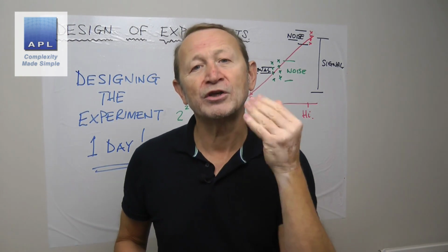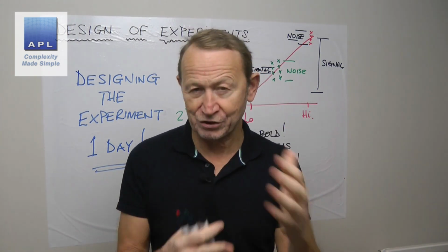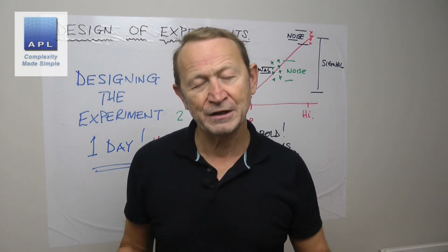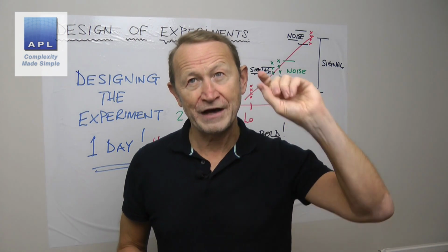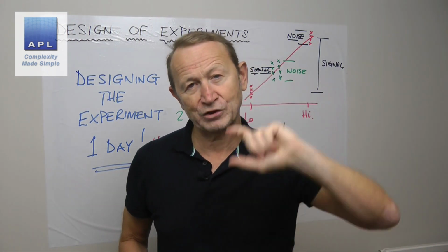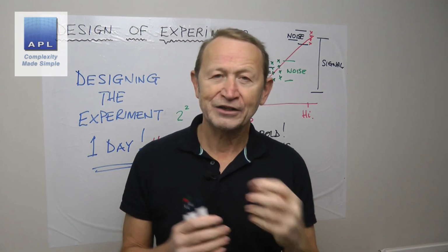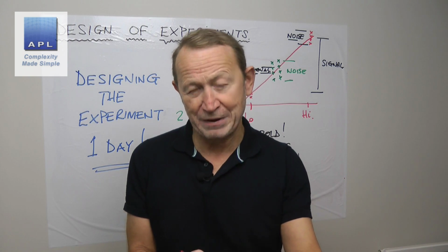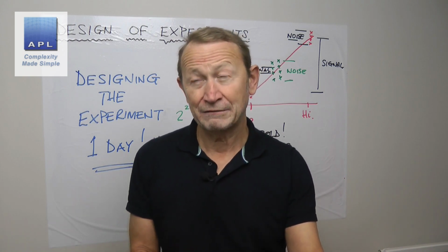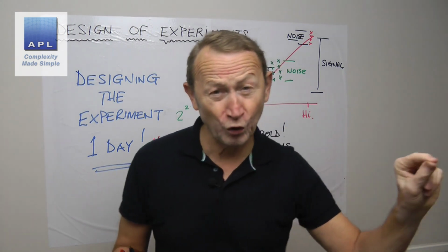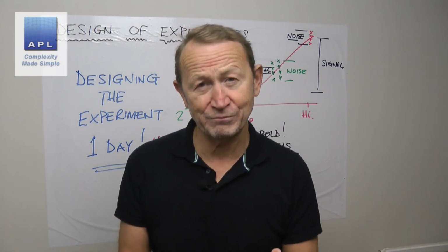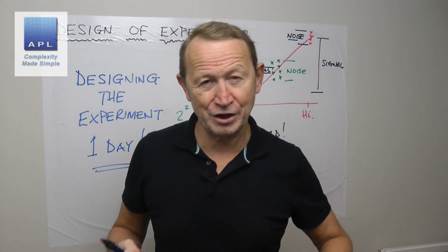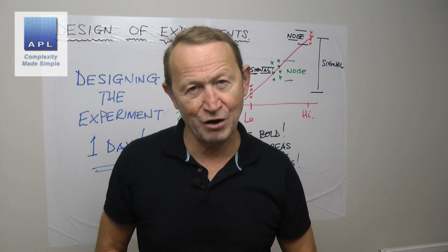Now, this is why you're going to spend a day doing this, because this conversation could take a long time with the experts. Maybe a technician gives you their maximum time, their maximum temperature, and their maximum pressure that they've ever had the machine on. But then you show them the DOE pattern and they say, yes, but I would never turn all three up all at the same time. Well, okay, we've got to turn all three up all at the same time. Where do you suggest we go?